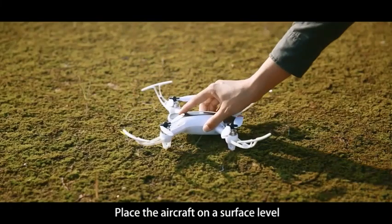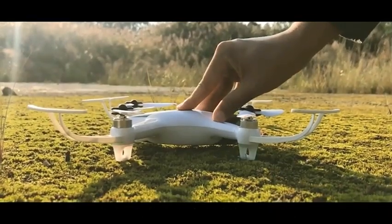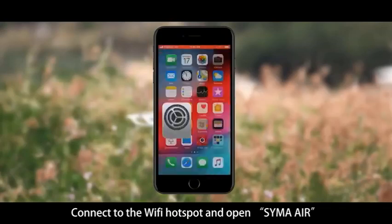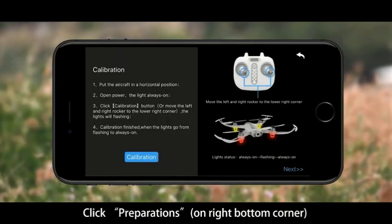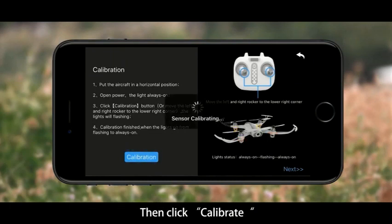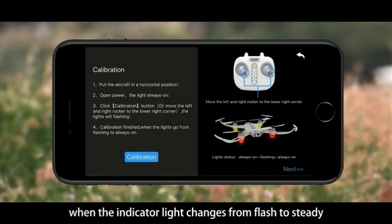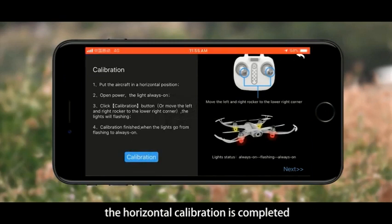Place the aircraft on a level surface. Switch on the remote control and the aircraft. Connect to the Wi-Fi hotspot and open Syma Air. Click Preparations at the bottom right corner to enter the horizontal calibration page. Then click Calibrate. When the indicator light changes from flashing to steady, the horizontal calibration is completed.